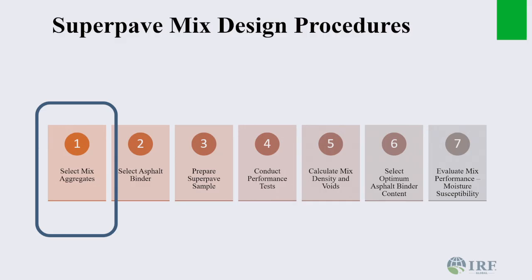Okay, then you will do an evaluation, and as you know, the moisture susceptibility of your mixture is very key. So you do that in the normal Marshall test to evaluate the moisture. So just those are the processes that we're going to go through.